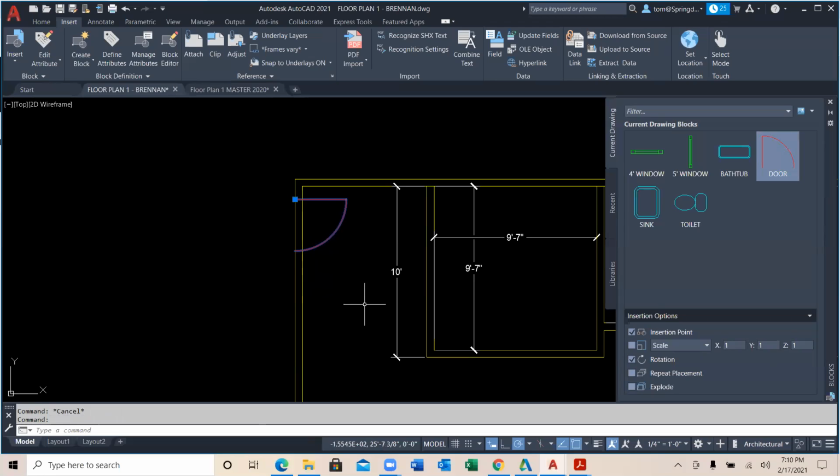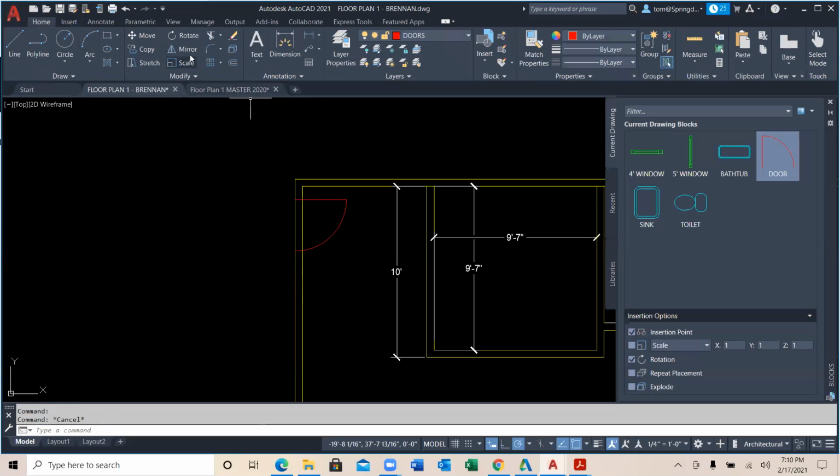Okay, so to mirror it, we already learned a little bit about mirroring, but I've got this right here. So what I'd want to do is mirror it. So I can go back over here, and we talked about the mirror command. So I can mirror it by clicking on this. When I click on that, I can then click on this location here, and I can go ahead and mirror it and go like that with it. That's the location I want it. Erase source objects? In this case, yes. Then I go ahead and go here, and I can use my control key and move it down, which is what I'm doing here. And just move it in position right there.